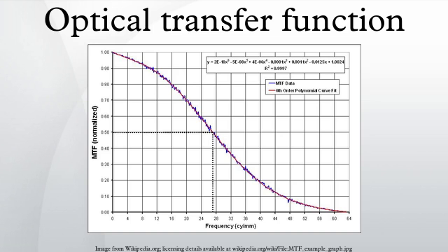Factors affecting MTF in typical camera systems. In practice, many factors result in considerable blurring of a reproduced image, such that patterns with spatial frequency just below the Nyquist rate may not even be visible, and the finest patterns can appear washed out as shades of gray, not black and white. A major factor is usually the impossibility of making the perfect brick wall optical filter. Such a filter is necessary to reduce aliasing by eliminating spatial frequencies above the Nyquist rate of the display.